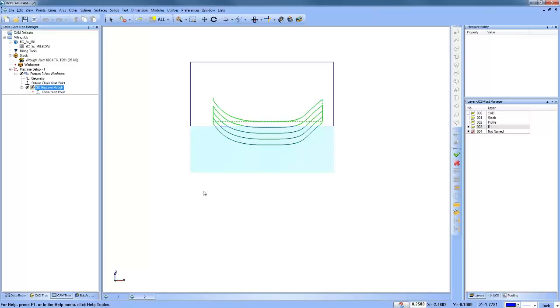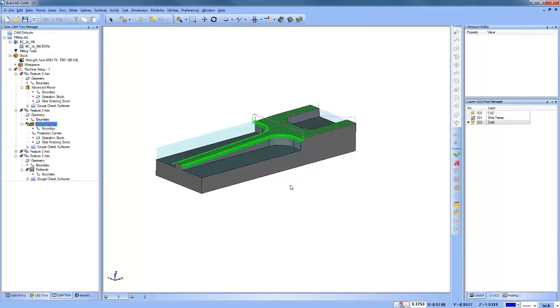Doug had a question: will the trim work with rotary axis? That's a great question. The Toolpath editor works with your 2, 3, 4, and 5-axis edits. I don't have a rotary example set up. You mean, again, where maybe you've indexed and cut away some of the material, and now you're on another side and trying to trim away toolpath? If that's what you're thinking about, Doug, then yeah, you could definitely do that.